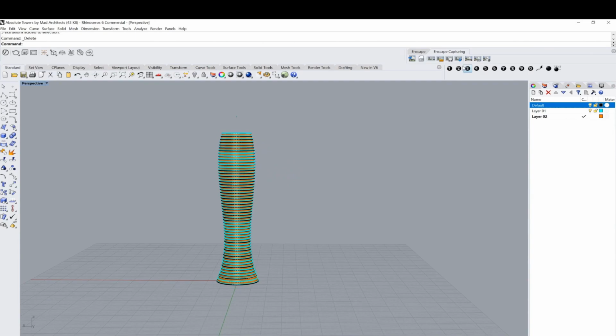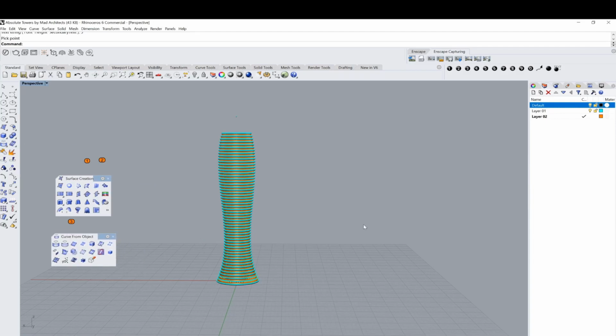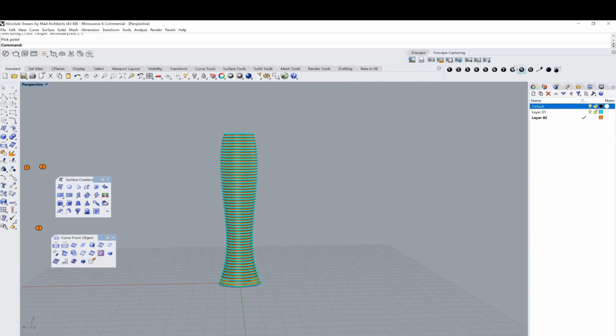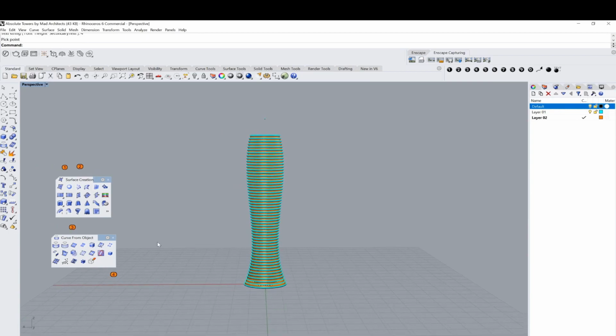Let us review what we learned. The first one, we used the curved lines to draw the shape form. The second one is we used the ellipse, this one, right? And the third one, we used sweep tool rules to create our surface. And then we used contours to make each floor's balconies and glazing, right? This is contour. Cool. This is all of the commands we use.